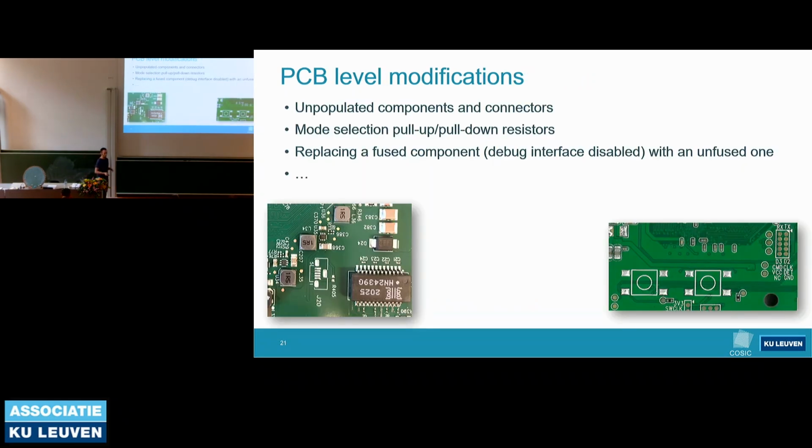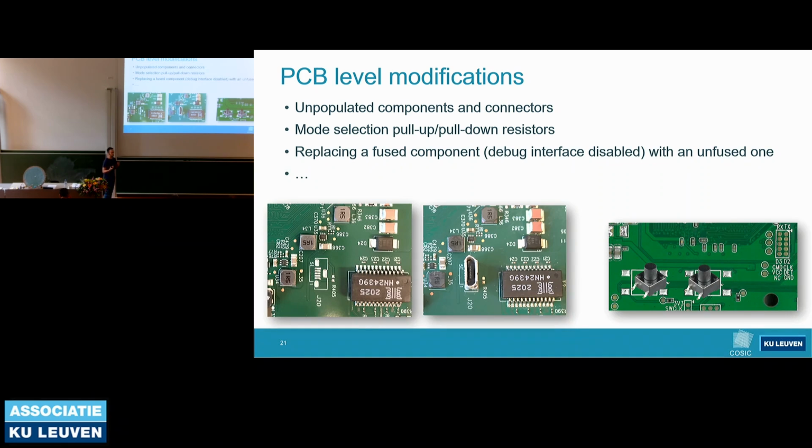Another thing we'll often see is if you open up a device, there will be a lot of components that haven't been placed on the board, that were maybe previously populated for developers, but not meant for manufacturers. So there have been many instances where I would open a device and would find an unpopulated USB connector on the inside of the device, something you would never be able to reach. This is an example here of such a USB connector that's missing. Of course, we can put it back, connect to this port, and see if there's anything interesting there. The picture on the right are some push buttons that weren't populated. So these, of course, you can also put back and see what the function is of these. You have to remember that typically these unpopulated components are used by developers, and that makes them interesting for us as attackers.